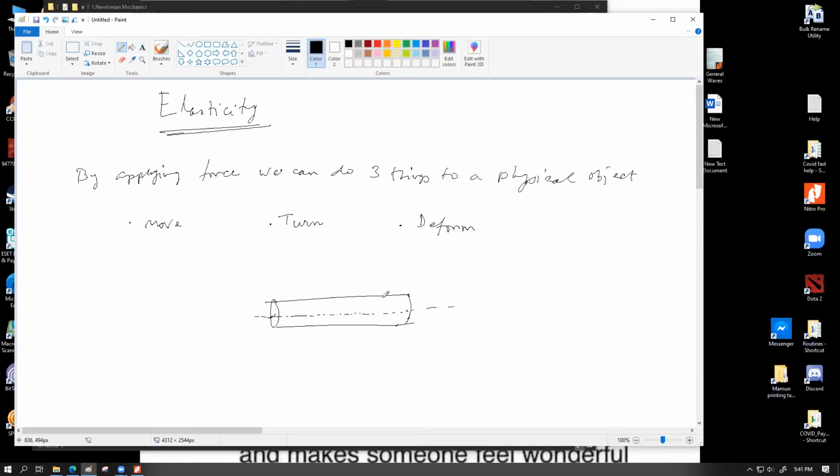Let's say we have one of these things over here, and we somehow apply some clamps, by human beings or by some machineries. If we apply two forces away from each other, this is what we call tension. Vice versa, if we apply two forces which are going to squeeze on the two faces, this is called compressive load, which is going to try to squeeze the object. Alternately, we can apply some load that will work perpendicular to the axis. For example, if we apply some load like this, it is going to cause the object to bend.